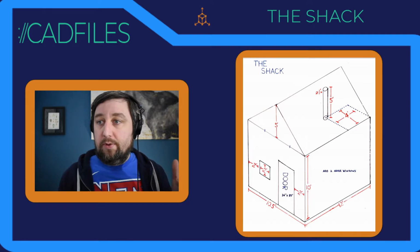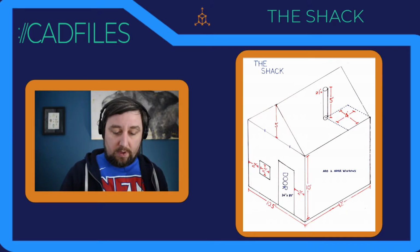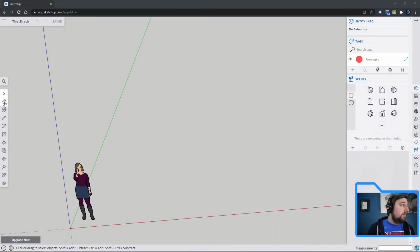I'll show you how to enter both ways, by 12 feet. All right, over here you'll notice on the left side your regular pointer, eraser, paint bucket, pencil for lines, arcs, rectangles. This is your press pull. This is orbit, and a bunch of other stuff. You'll notice that there are little arrows next to it. So if you can't find things right away, sometimes they're in the little hidden menu next to it.